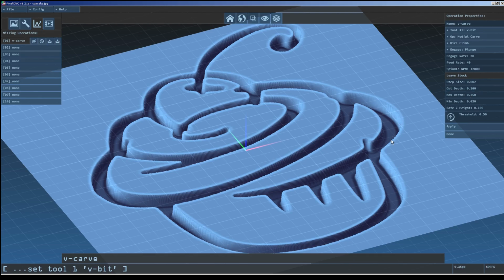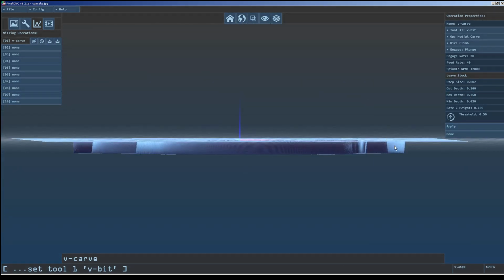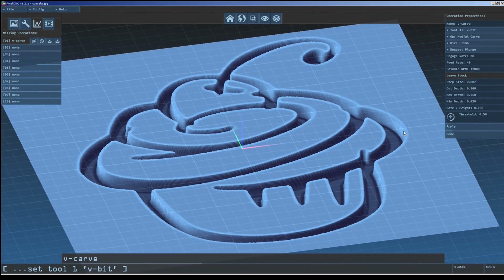use a smaller one, and our generated toolpath will include multiple cut passes to retread any cuts until they reach the depth necessary to recreate the shapes in our image. We'll also set our max depth to 1/4 inch. Allowing shallow cuts is important for reproducing sharp corners in a V-carving, so we will set our minimum depth to 0 to allow shallow cuts.